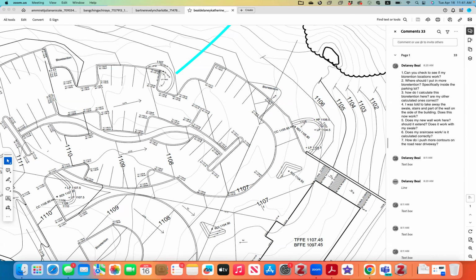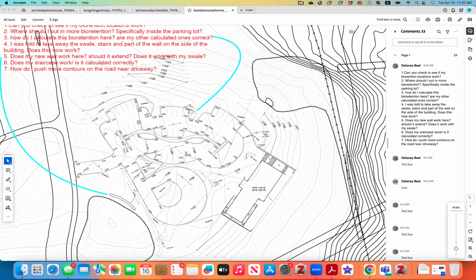But you need to have a trenching along this line to be able to make it work. Okay. So that water will be directed out there, and this collects all the water coming from the top plaza. Yeah, that's a good way to separate the plaza and the driving area. Okay, so that is on this side.